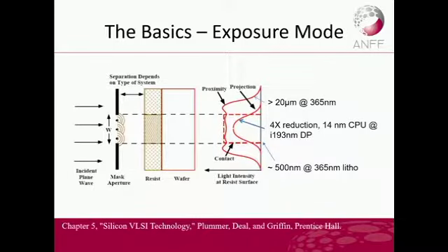So here is just the transfer, the light intensity at the resist surface from the mask, to show you what sort of light profile you can get at this interface. With contact lithography, you actually lose nothing. You get a nice square wave. In our lithography system, you can pull off about 500 nanometer, depending on the thickness of resist you use and the type of mask, of course.